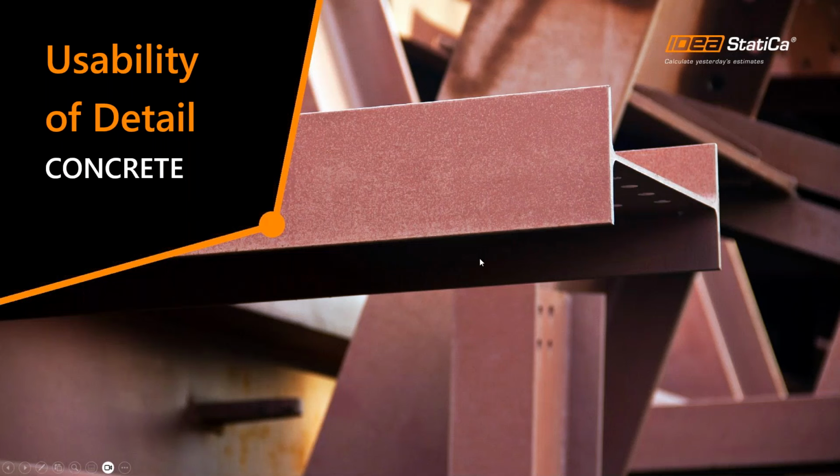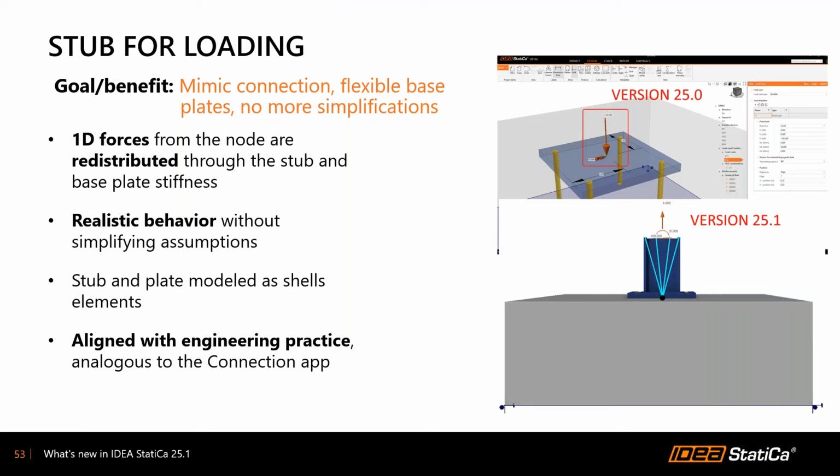So let's follow up with the usability of the Detail. I was mentioning before that we also did some improvements regarding the stub and the local coordinate system on the base plate. So let me start with the stub for loading. So Detail 3D now introduces the stub for loading, a short column segment that receives full 6 internal forces at the single point and redistributes them physically through the stub into the base plate and to the anchors and the concrete. So what are the benefits?